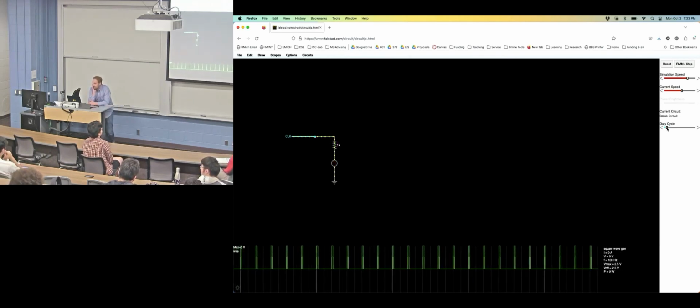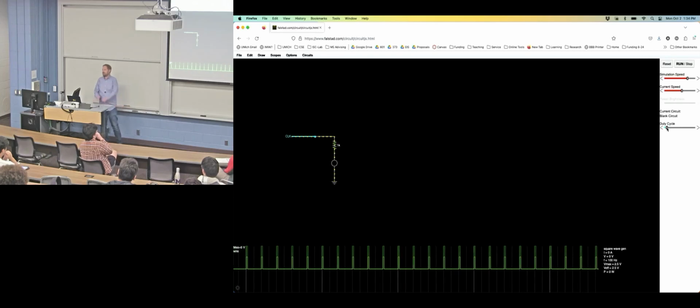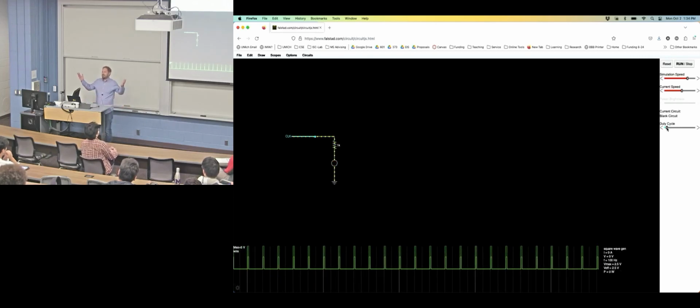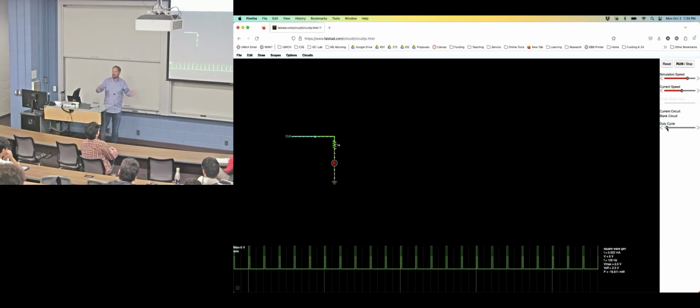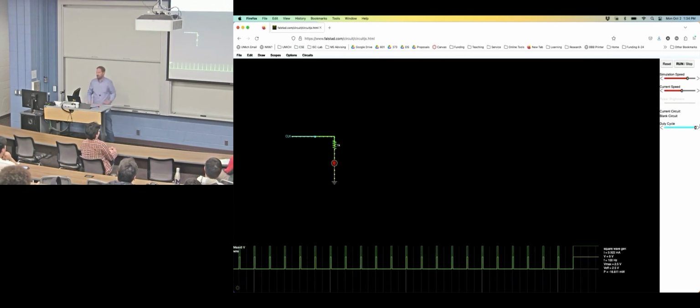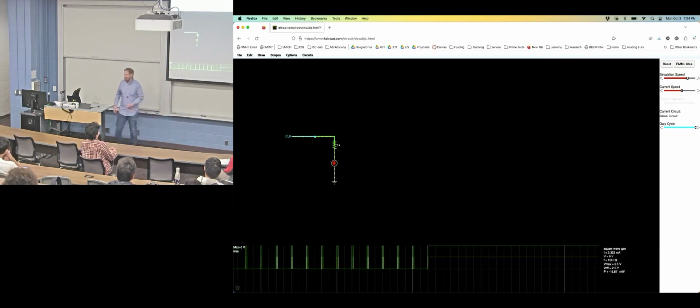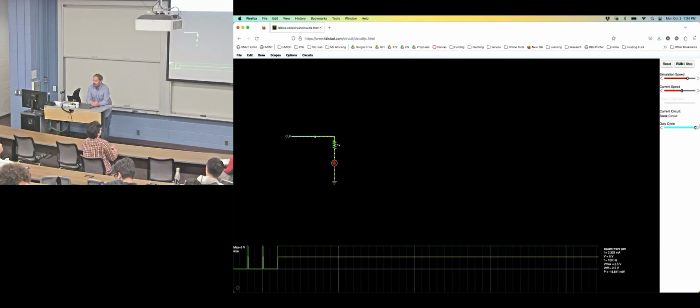How bad would it be if we just sent that average voltage to the LED directly without a clock? That would be fantastic. How are you going to do that? Directly to... All right, you got an STM32? How are you going to do it? You could use a GPIO pin and just send that voltage out. Oh, I see what you're saying. You want to do this? Yes. Fine. Put a resistor there. I just chose 1K randomly. A standard one is 330 ohms, but you could do your Ohm's law equation, figure out how to limit how much current goes to that thing.